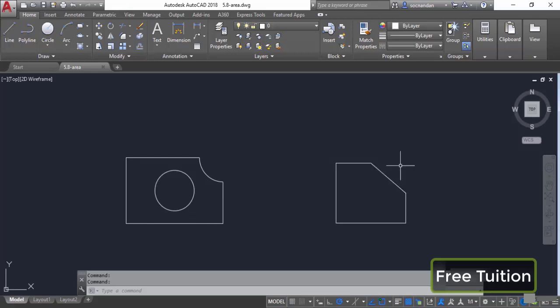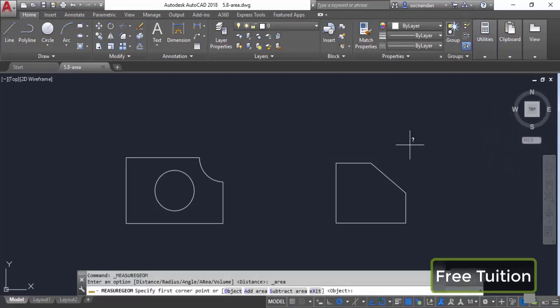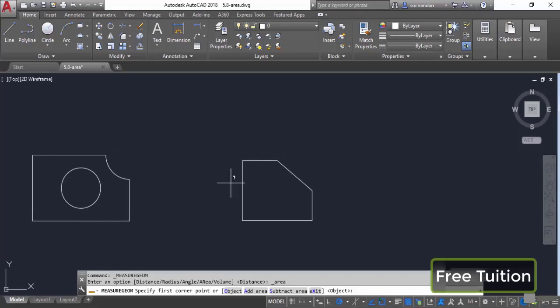And for that, once again, I'll go to the utilities panel, and from here I'll select the area tool. In the previous video, we saw these inquiry tools, and now in this video I'll tell you about this area tool. So select this area tool, and now you need to specify the area in your drawing. Here I'll select this geometry first. Let's say that we want to find the area of this complete geometry, and for that I'll start with any point. Now click at the second point, then the third point, fourth, and the fifth. Now we have this green window, and the complete area which is enclosed in this green window can be seen directly using this command.